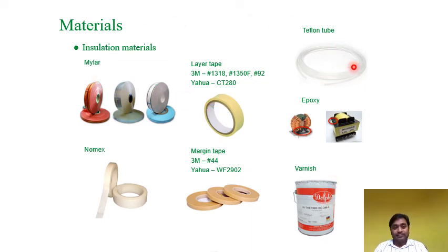So this material is really very important. We need to make sure that if our component is a UL insulation system followed component, all these materials are certified by the UL agency under that particular UL insulation system, and then only can they be used. So with respect to safety requirements, this is a very stringent requirement. We need to see what the different ratings for the UL are, and if it meets them or not, especially thermal ratings, temperature requirements, flammability requirements, etc.